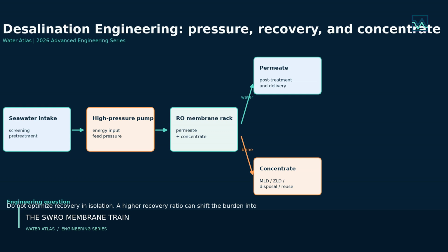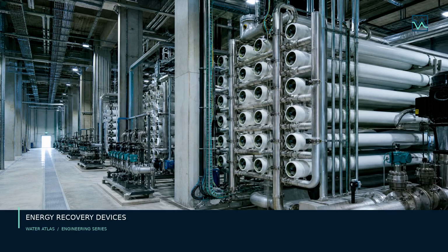Through the optimized integration of isobaric energy recovery devices, or ERD, and high-efficiency pumping trains, state-of-the-art seawater reverse osmosis plants operating in 2026 have pushed specific energy consumption, or SEC, down to less than 2.5 kilowatt-hours per cubic meter of permeate produced. Yet, engineers must remember that this figure is context-dependent. High salinity feed water, colder water temperatures increasing fluid viscosity, and smaller plant capacities will naturally elevate SEC beyond this baseline.